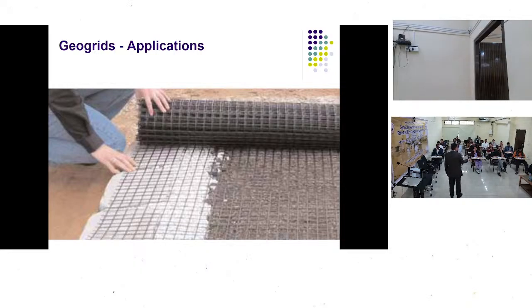And when we design these slopes, what we see is that whichever slip circle is formed has a factor of safety of more than 1. As per design, we say the factor of safety should be more than 1.5. That's how we define the slope. So when I'm using this geogrid as a reinforcement layer, I lay this horizontally in my slope when I'm going for a reinforced earth wall.